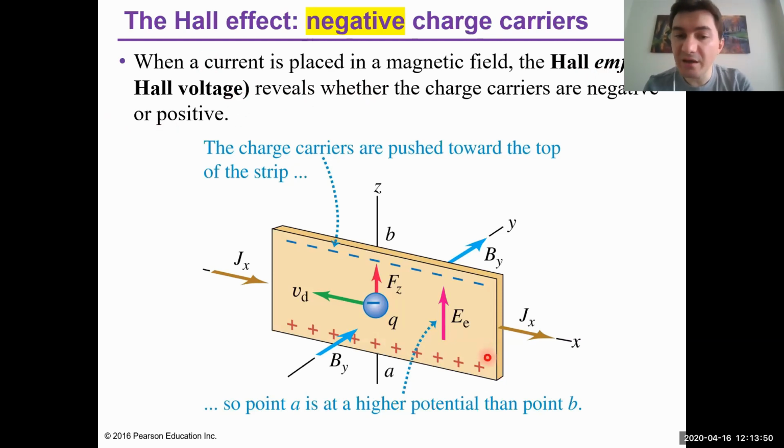Okay, at the beginning there is no voltage difference, we just have a current. This is the current density, and electrons have that type of drift velocity opposite to the current density. Then you apply a magnetic field, and electrons will be collected here, positive charges will be collected here, then there will be an electric field in the system. So we produce a Hall voltage here in between. So this is also called Hall EMF or Hall effect, okay?